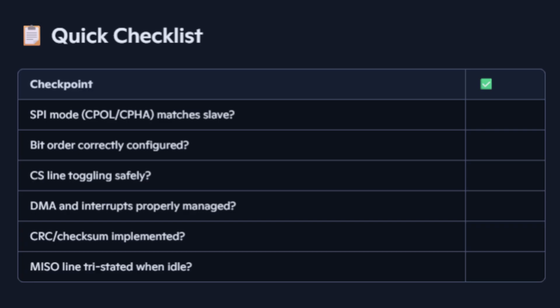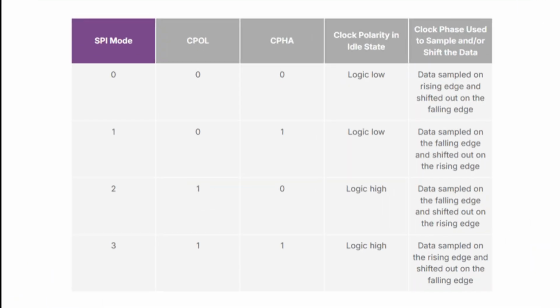4. Use debug pins or logging. Toggling a GPIO pin before and after SPI transactions, or logging key steps, can be invaluable for debugging intermittent issues later using a logic analyzer or trace tool. It's about building layers of checks and recovery mechanisms on top of the basic SPI communication. That makes sense. Add the intelligence in your application code.